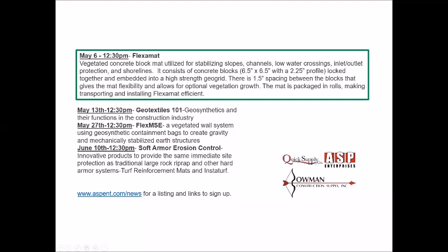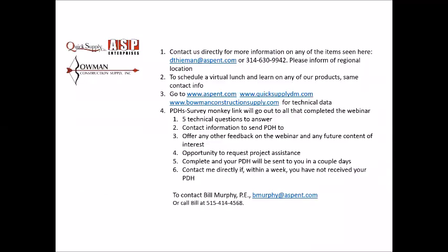Anything else you want to say about that, where you run into people that feel like they already have an opinion of certain products? Yeah, and hydroseeding's been around since the 1950s, and it was designed initially to get even distribution of a variety of seeds on your site because it keeps it in homogeneous slurry. Real hydraulic erosion control products were not around until the early 2000s. So that's really typically when we started seeing these engineered products that are designed to withstand heavy rainfall events. And that's really the biggest differentiator.